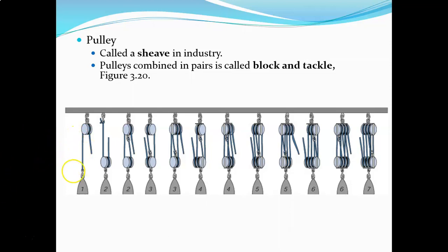So we've got the fixed pulley overhead, and we're standing beside the load. If we're pulling down on this rope, it's all in relation to gravity of how we're pulling, okay? Gravity has full control over that weight. So this pulley is really not giving us any mechanical advantage because as we pull down, we're having to pull the same amount of weight that the load weighs.